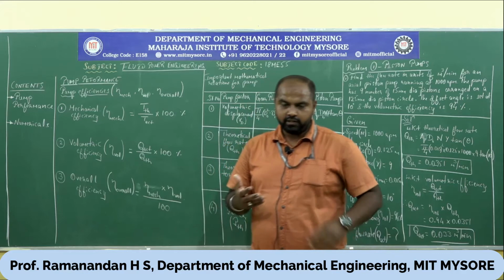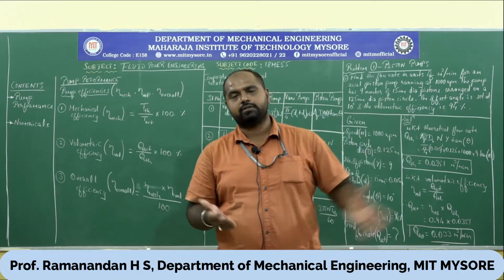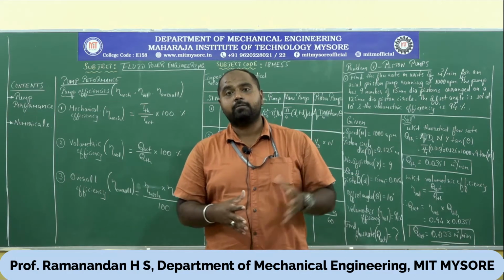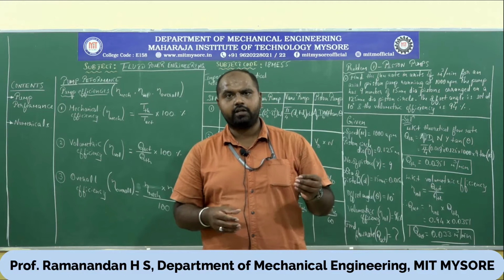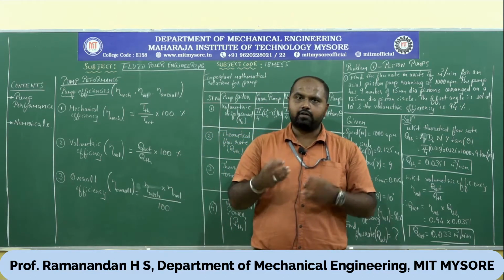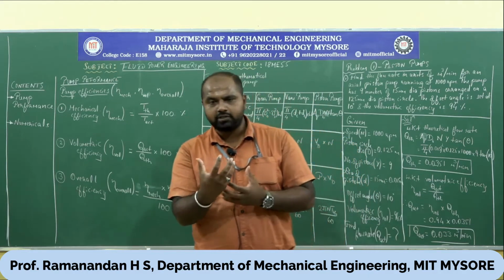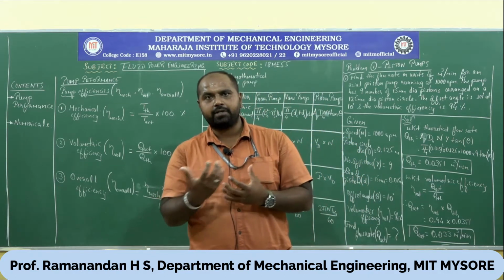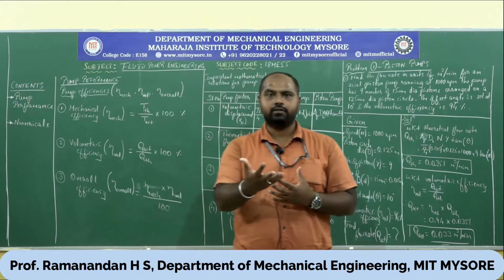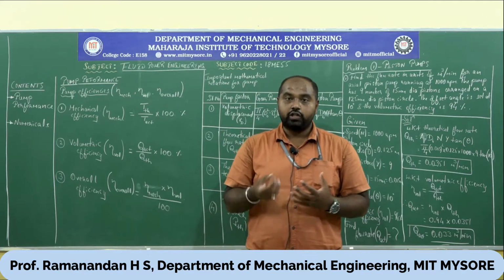Usually the material selected for the pump, with the tolerance or clearance, plays a vital role in the performance of the pump. What material you choose to make the gears or vanes or the casing, the prime elements contributing to creating the pressure and the flow, which are actively involved with the circulation process of the fluid or discharge, plays a vital role.